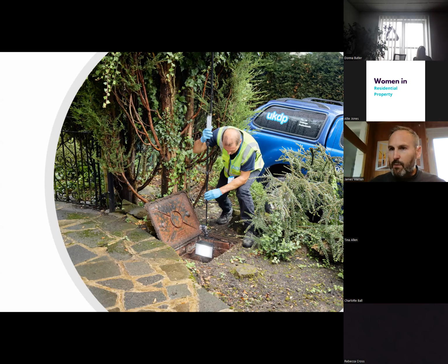It should be sitting, as we saw on a previous slide, where there's an outlet pipe. If you think of that as a clock face, the liquid level should be sitting right at the bottom, at about 6 o'clock. Now, if we look inside the tank and it's sitting above that level, that's a sign that the water can't get away. So there might be a blockage, a collapse, or complete soakaway failure.